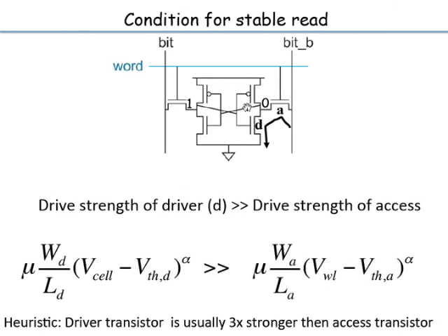But it's also not necessarily the case that large cells lead to lower delays, because if I have the same size memory, if my cell area is large, then the overall size of the memory also becomes very large. So the wires also become very long. So wiring delay goes up. So it's not a very straightforward thing to say that just increasing the size will work. But in general, increasing the size increases the drive strength. So you can expect some reduction in the delay.